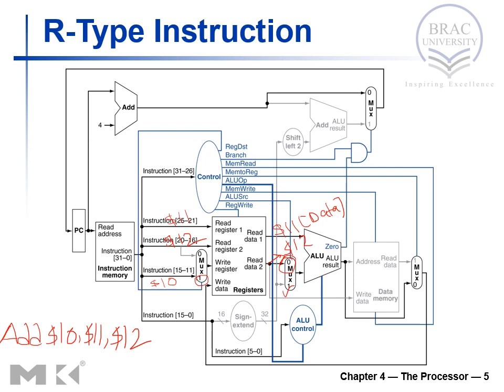So we perform the arithmetic operation, and ALU OP would send ALU control the 2-bit signal, and based on that it would generate a 4-bit signal that would let the ALU know that it needs to perform addition of the values coming from register 11 and 12.